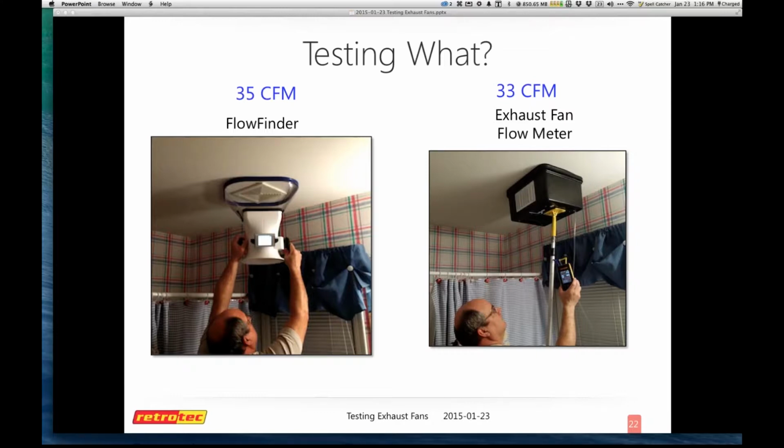All right, I'm going to step through how you go through the gauge and the setup. On the right I have an exhaust fan that's just upside down, so I can use it for demonstration. And on the left, I'm showing you where I'll be at the end, which is how to use two connections so that you can always read the pressure going into the device itself. On channel B, it gives you the actual results, how many CFM is moving through the exhaust fan as you're measuring it.